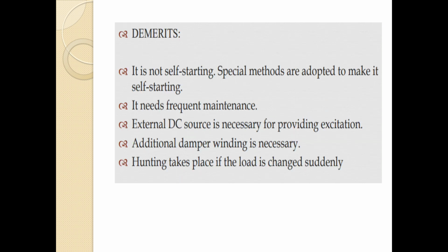Demerits. The first one is that the machine is not self-starting. It needs frequent maintenance, and external DC supply must be given to the rotor circuit. Additional damper winding is necessary, and the hunting effect is a very large problem of the synchronous motor.